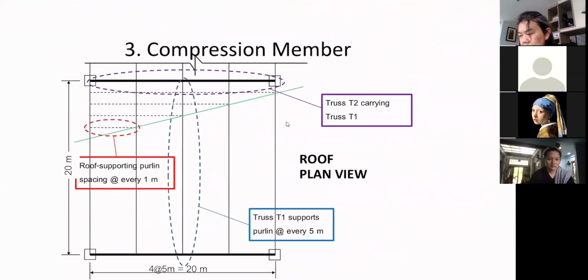This is the plan view. You can see that if you look at the main truss like this, that's the main truss. The plan view will show that if this truss, say it's a main truss, doesn't support any purlin, the only brace point that this truss is going to have is where a member comes in to help prevent the lateral movement of the top chord.